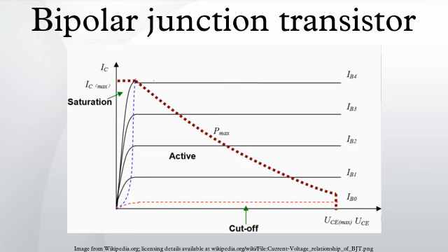Amplifiers: the transistor parameters alpha and beta characterize the current gain of the BJT. It is this gain that allows BJTs to be used as the building blocks of electronic amplifiers. The three main BJT amplifier topologies are common emitter, common base, and common collector.